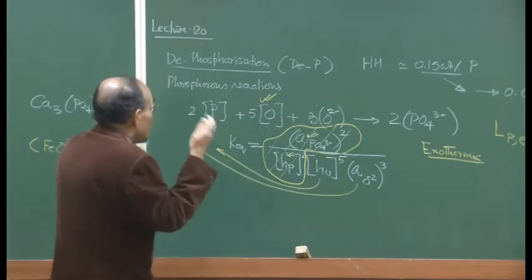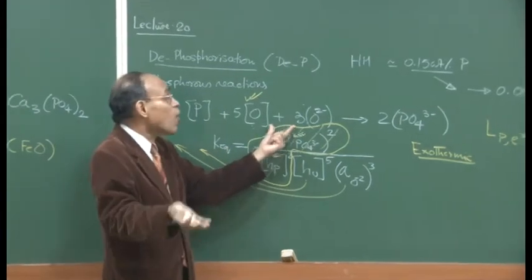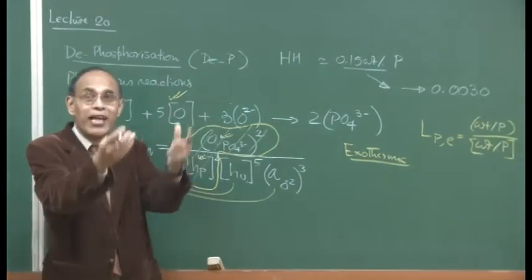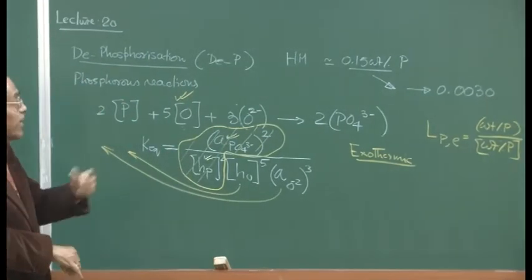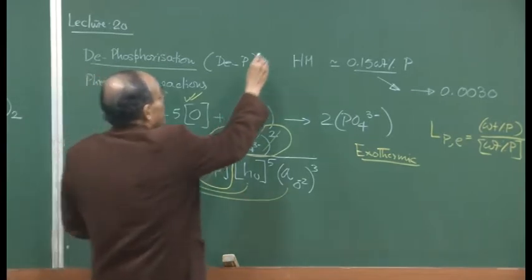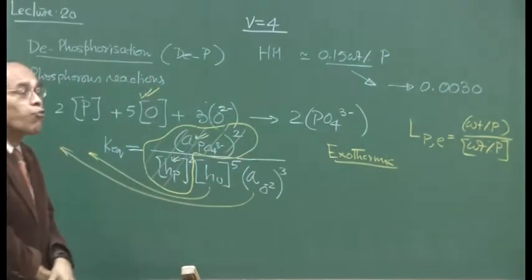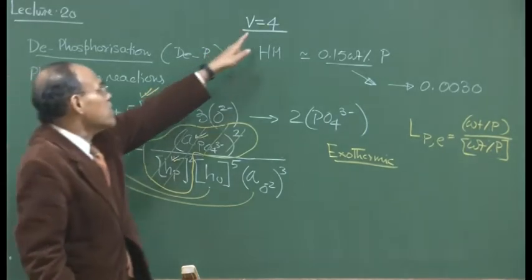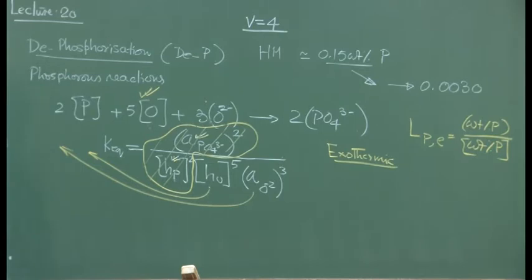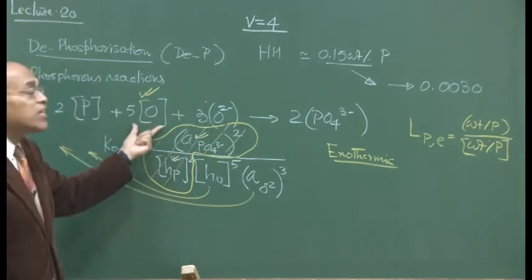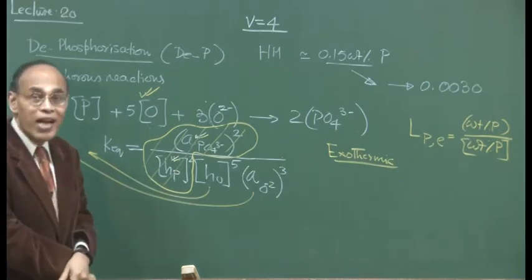Okay? And all these metalloid reduction oxidation reactions yield an enormous amount of heat, and therefore we can add a very good amount of lime into the system, yielding a basicity of the slag, or a V ratio, which can often approach a value of 4 or so. So this high basicity value, together with the intense oxidizing environment, facilitates phosphorus removal to a large extent.